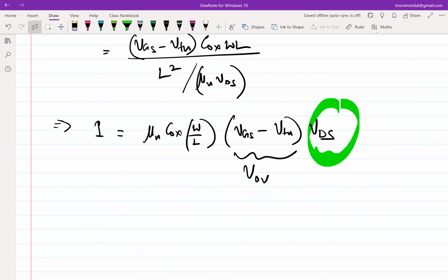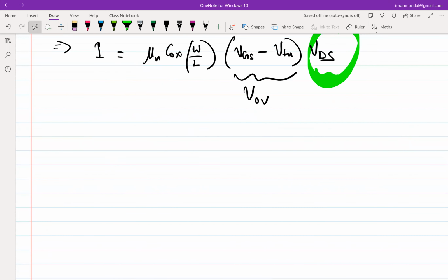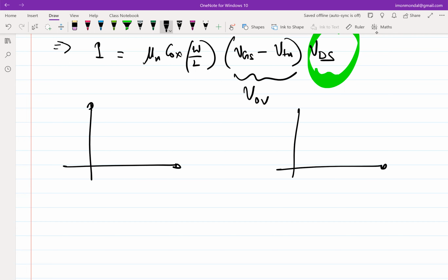Okay, fine. So now we are circuit designers, so we'll have to get back to our Y parameters, right? A quick recap: what was the required IV characteristic for a two-port network for us to get amplification? Y21 should have been high, and Y22 and all the others should have been 0, right? Which essentially means that if I plot these four curves,